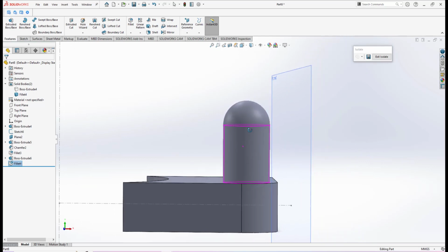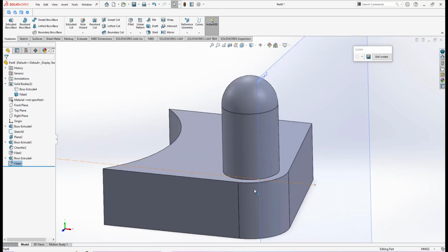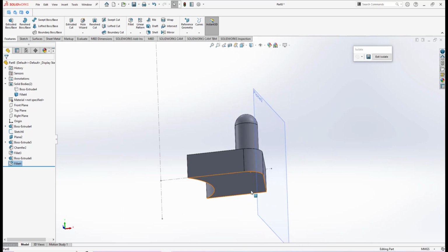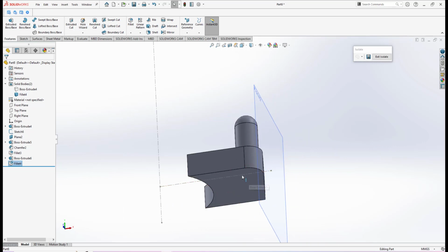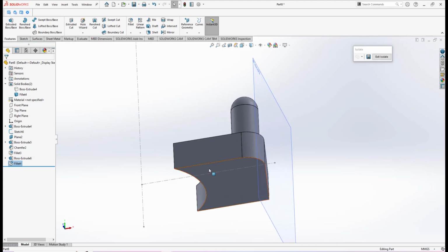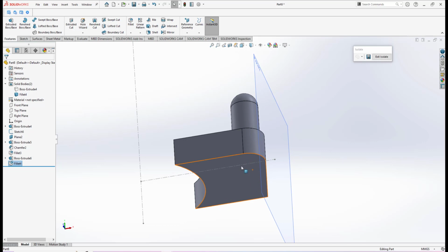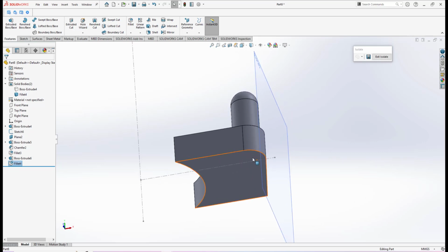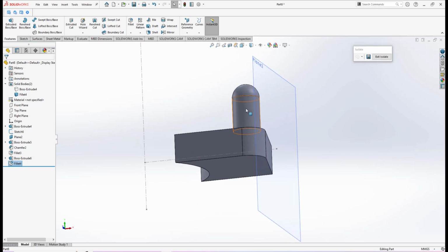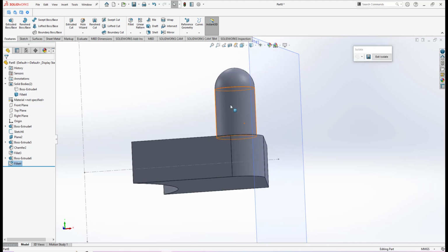The idea of having this pin on top of this arm is that later I show you how I insert an M1.5 screw and also a blade, because the blade will be attached at the bottom surface here. I will attach the screw on the bottom plane of the blade, and I will do combine subtract to make the inner thread here, since the screw has an external thread.